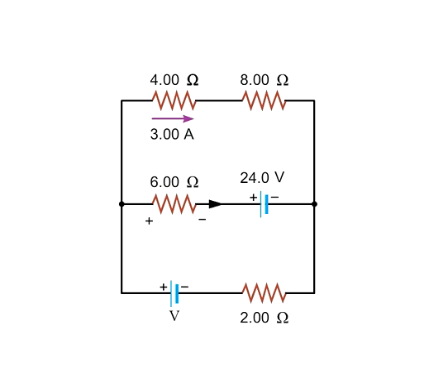These signs must be consistent with our choice of direction of the current, which flows from higher electrical potential to lower electrical potential. In the top loop, the current is shown to move from left to right in the upper part of the loop. We will place plus and minus signs on the 4 and 8-ohm resistors to indicate the high and low electrical potential ends of the resistors. Again, these signs must be consistent with the direction of current, which we assumed in that part of the loop.